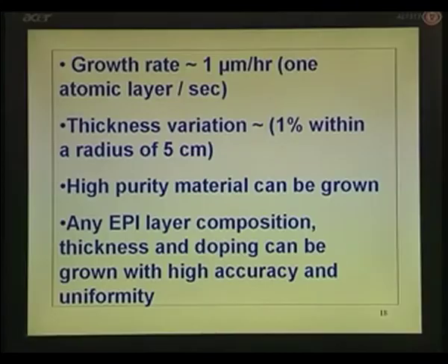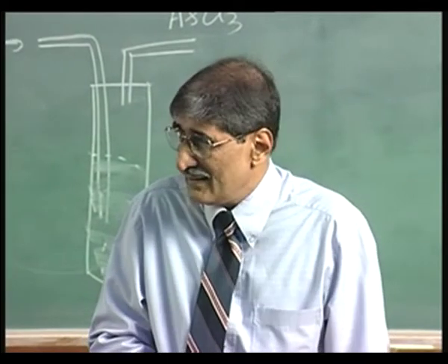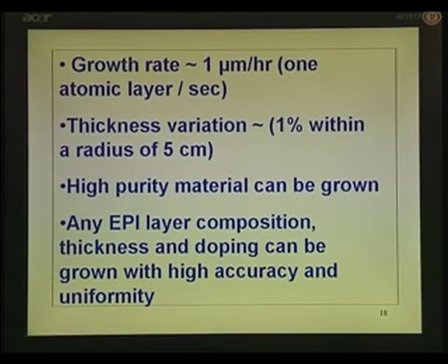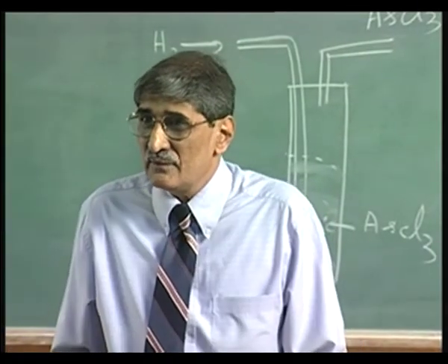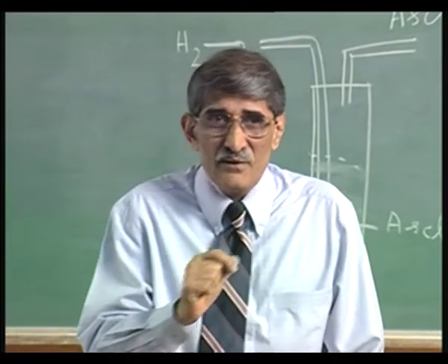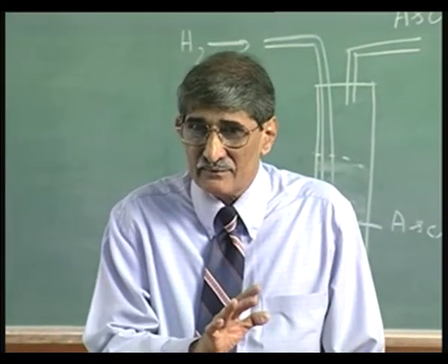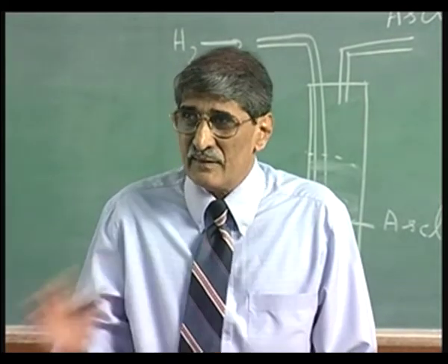Now, that is the pumping system, and the advantage here is you can grow 1 micron per hour, very small growth rate you can do. When you grow at a very small rate of growth, very high purity, excellent crystal quality you get, okay, and thickness uniformity over a 5 centimeter wafer you can get within 1%. So, people who want to make quantum wells, very small layers, they resort to this. Today, MOCVD is competing with this to grow thin layers. Okay, let me just warn you and leave on that. That is, MBE is very good, MOCVD is competing, because if you want mass production, MOCVD is better than this.